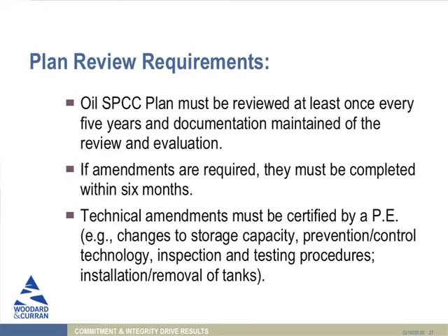But if you do your review and you find that amendments are required, they need to be completed within 6 months. And any technical amendments, things such as a new tank, a change in secondary containment, new inspection procedures, need to be certified by a PE, again, unless you're going with that qualified facility route and doing it yourself.